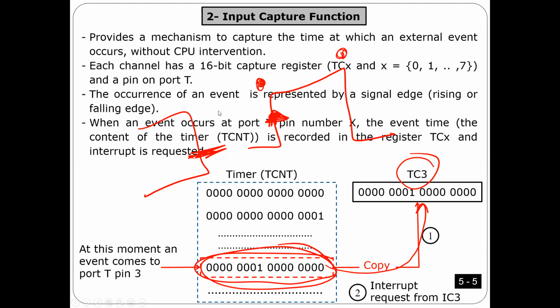Just take it and store it in a memory location. Otherwise, next time there is a falling edge, it is going to be overwritten. Then when the second one comes, I do the same thing, and once I have the count here and the count here, I can do the calculation.